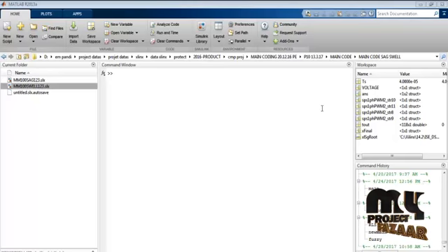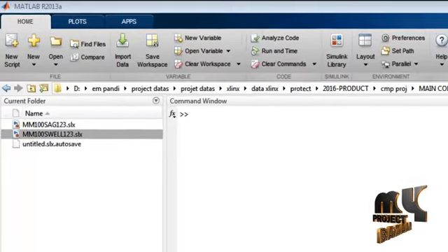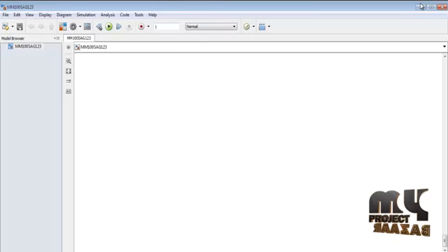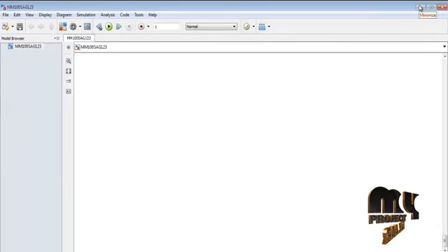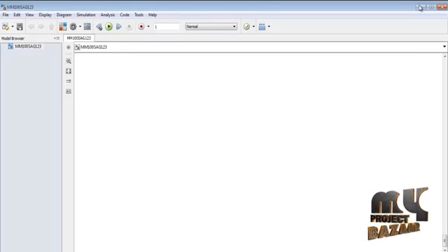This proposed implementation is done in the MATLAB simulating environment. First open the MATLAB window and create a new model file. After creating the new model file, we arrange the elements as per the given flow diagram from the simulink library browser. In the library browser, we used two toolboxes: one is the simple power system toolbox, and the other is the commonly used toolbox. From those toolboxes we get the elements and arrange them as per the given flow diagram.